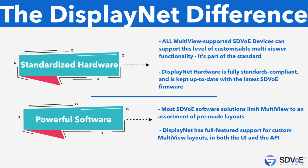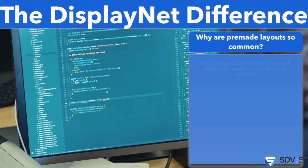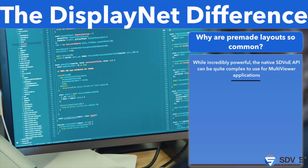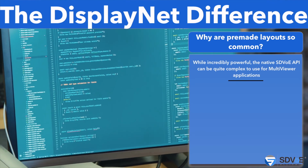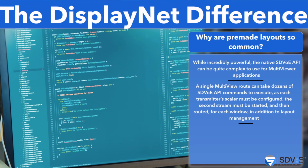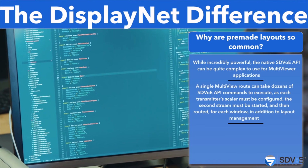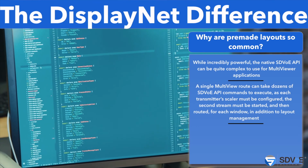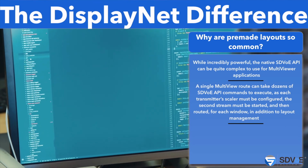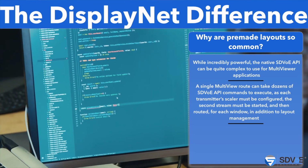You can programmatically create layouts with the API that we've created. Now, why is it so common that you would have this advanced multiviewer functionality and then limit the integrator to pre-made layouts? Well, the SDVoE API is a very good platform. It's very flexible. It can support those kinds of applications that we discussed earlier, but it can be quite complex to use, especially on an integrator layout for multiviewer applications. A single multiview route can take dozens of SDVoE API commands to execute. As each transmitter scaler must be configured, you need to start the second stream and then route it for each of the windows on your receiver.